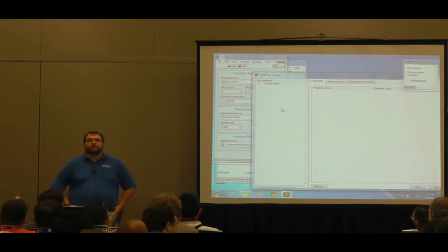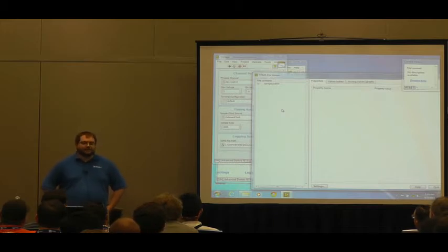Okay. And then I have one more question. If you have like 2 DAQ tasks, can you stream them both to the same TDMS file at the same time? No. So the DAQmx TDMS streaming streams to 1 file per task. You can't merge 2 tasks into 1 file.